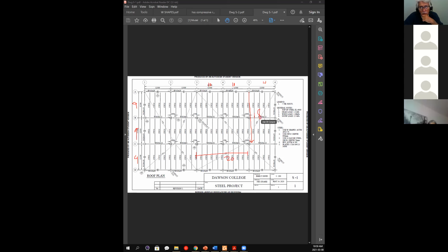Exactly. So what's 20,000 times 0.02? That's 400. Okay. And then we want to put the shoe of the joist on top of that, so another 100. Therefore, here we're going to drop 500. That's what I did exactly. So here is minus 500, Omar. Now, if this is minus 500, what would this one be? 250. It's exactly halfway.